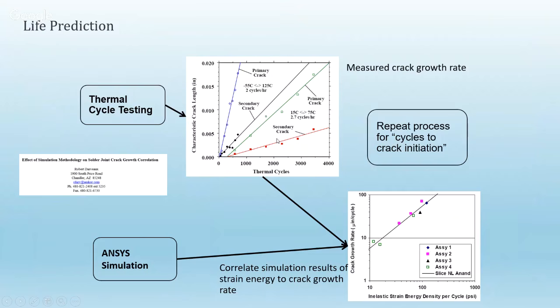With a series of different chips, geometry, and solder, you can then, in this case, slice open the solder and track how far the crack has grown over how many cycles. So, get a big batch of packages, start cycling them, and periodically pull some out, cut them open, and see how far the crack has grown. This was what Robert Darveaux did at Amkor to describe this particular process.